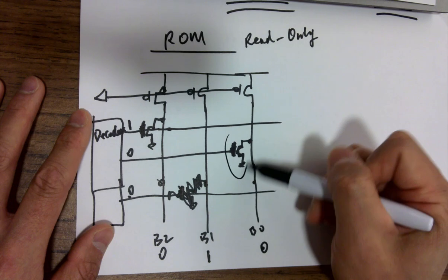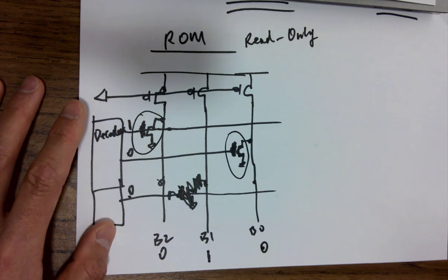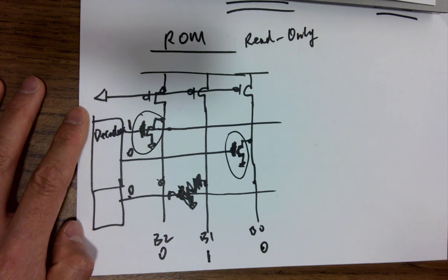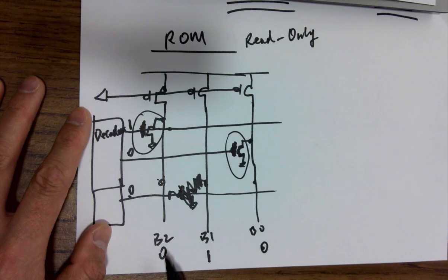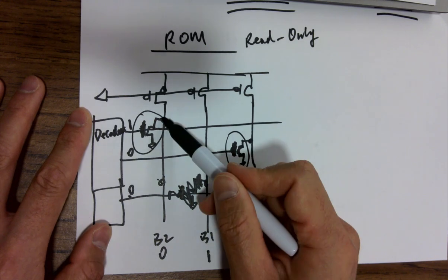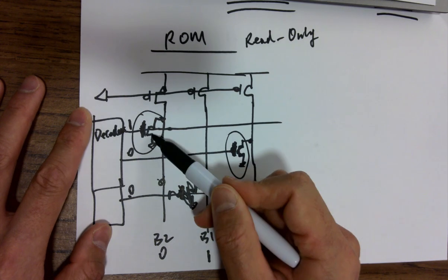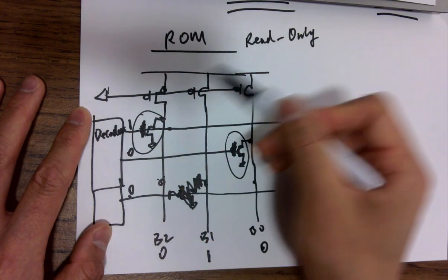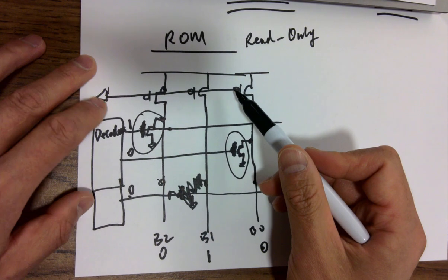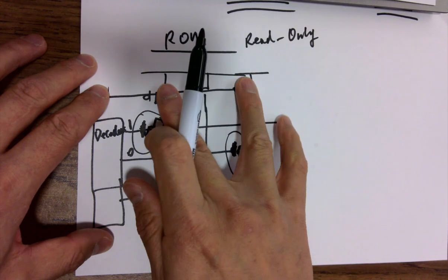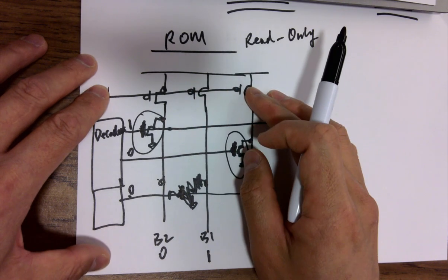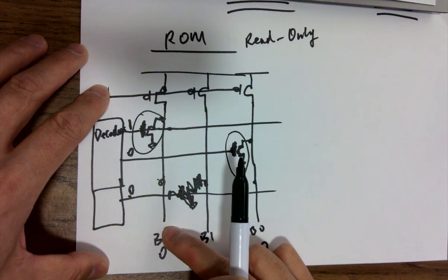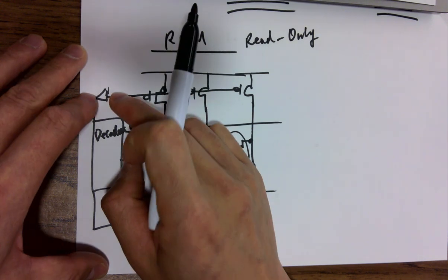Because these are strong NMOSes. So it's 0 because this here is grounded, even though this is open. You can disable the reading by giving a 1 here, but now we are reading it, so ground gives a 0 here. So these are all on from VDD. I think you can control this pin here, but it doesn't matter.